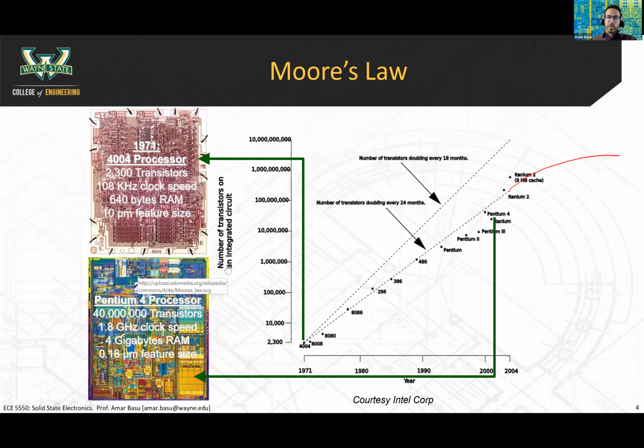That includes having multiple cores on microprocessors, having better power dissipation methods, making smarter architectural decisions, and so on. There's also the possibility of going to single electron transistors, which is a topic for a different course, but that is kind of like the ultimate limit of miniaturization.